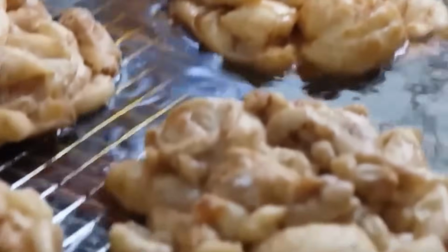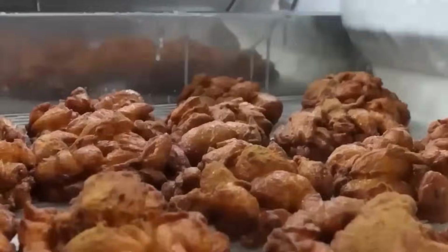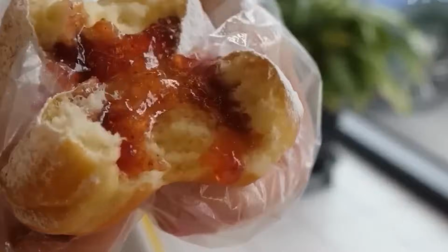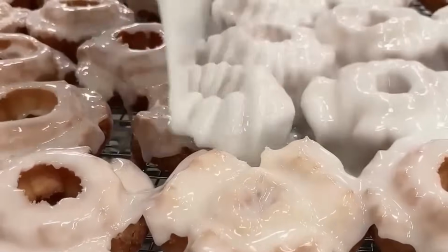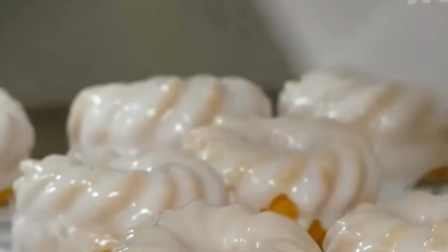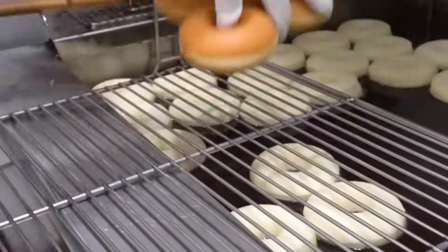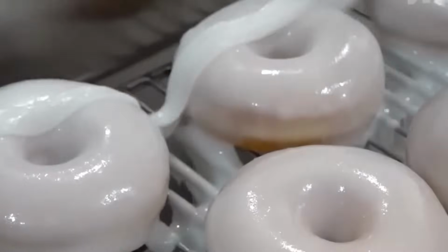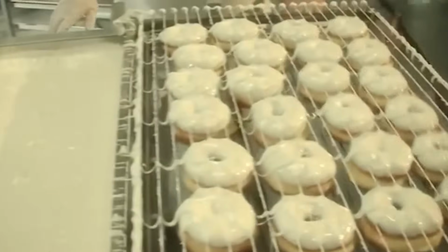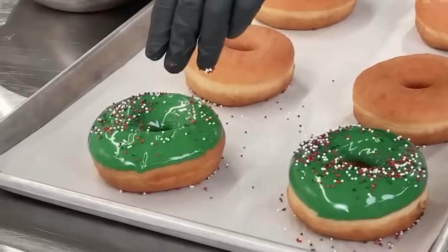Each completed pallet is wrapped with stretch film using a rotary arm wrapper. The arm spins around the stationary pallet, tensioning the film for secure transport. Film overlap and wrap count are controlled digitally to match load size. Wrapped pallets are labeled with barcoded identification tags applied by robotic labelers. Pallets then enter a gravity-fed conveyor line toward refrigerated loading docks or cold storage.